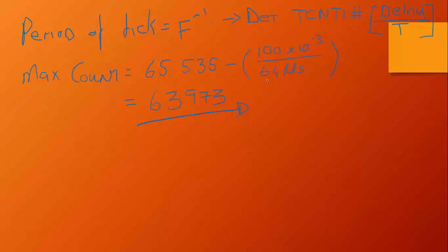So we start by getting the frequency. We know that we've got 16 megahertz, and we divide that by 1024. If we do that math, it is going to give us 15,625 hertz, so it's 15.625 kilohertz. This is the frequency that the counter will see as its heartbeat.